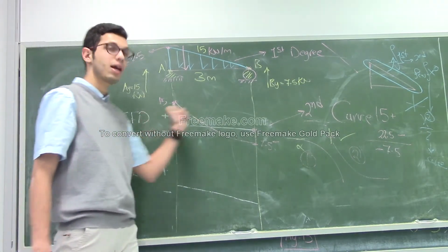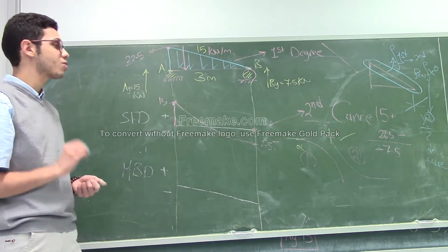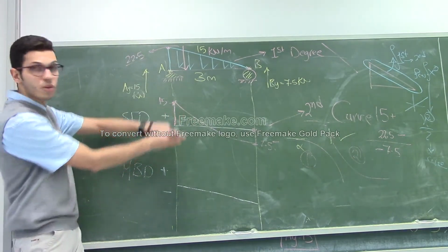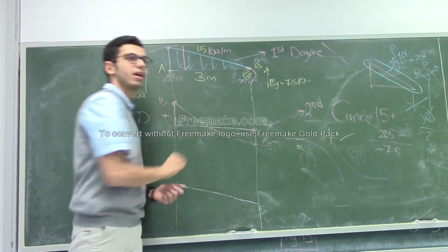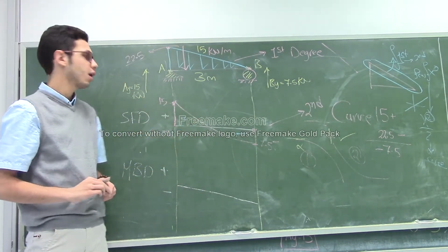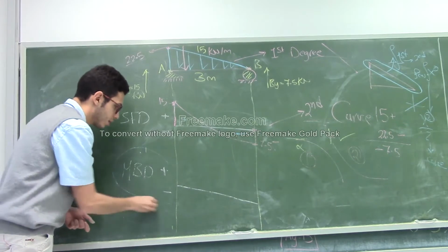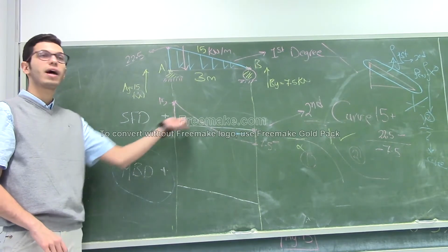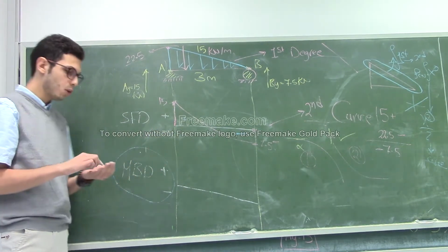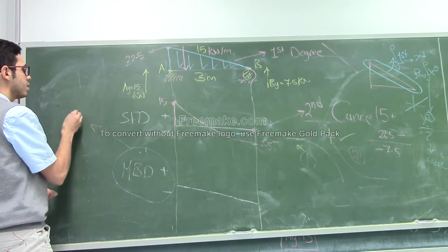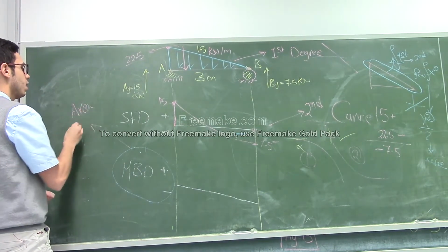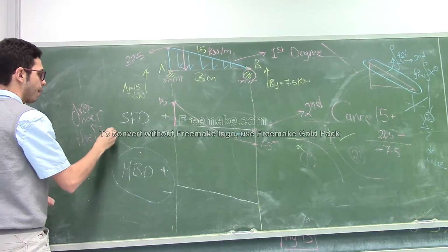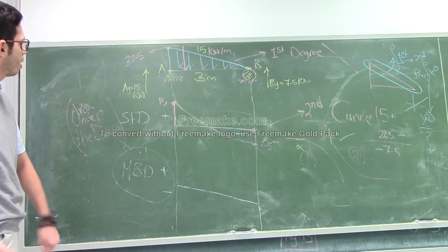Now, after we calculated the shear diagram, we should focus on something important. All of us agree this is a positive area, right? Yes, because it's in the positive region. And this is a negative area because it's in a negative region, right? And all of us agree that, at the bending moment diagram here, the moment is the area under the curve, right? You remember this one. What is the meaning of the moment here? The moment is the area under the curve. It's the area under the curve.